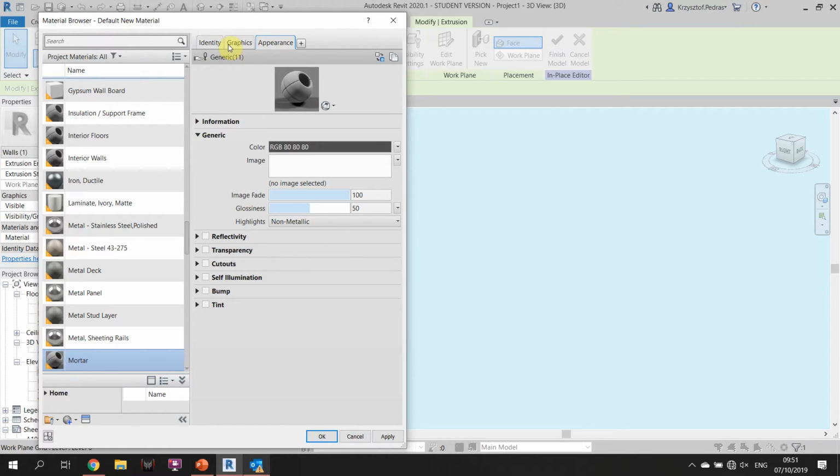If we switch to the appearance tab, I'm gonna show you a second way to apply material to it. Meaning that we could either choose a color, a texture that we import, or we can use something that is already inside of the Revit files. Right here, lower corner, you have an option to open and close the asset browser.